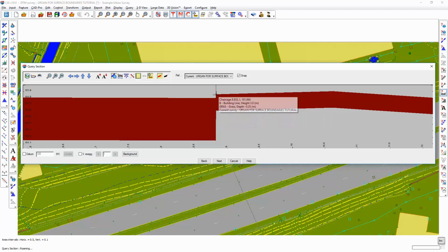or we need to create an additional link just inside the boundary for each surface so that we don't end up with a vertical line between these two differently heighted surface features, because the machine control systems wouldn't handle 2 points one on top of the other.